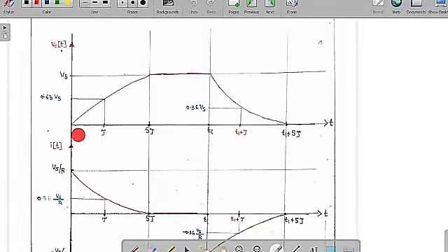So you can see clearly here, this is called the charging mode. In the charging mode, the capacitor voltage is going to increase with the expression Vs into 1 minus e to the power of minus t by RC. By this expression, it increases in a very slow manner. At t is equal to tau, we can say clearly it is going to reach 63.2% of the final value, so it reaches 0.63 Vs. Now at nearly 5 tau, it is going to reach nearly 99.99% of the steady state. Because of that reason we say 5 tau is the steady state value, meaning within this time it reaches 99.99% of the final value.